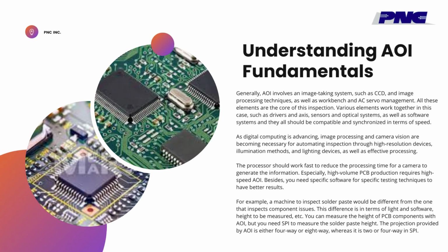Understanding AOI fundamentals. Generally, AOI involves an image taking system, such as CCD, and image processing techniques, as well as workbench and AC servo management. All these elements are the core of this inspection. Various elements work together in this case, such as drivers and axis, sensors and optical systems, as well as software systems, and they all should be compatible and synchronized in terms of speed.